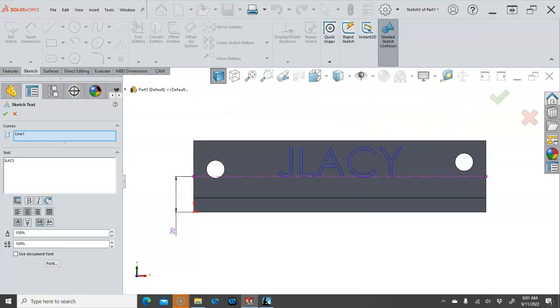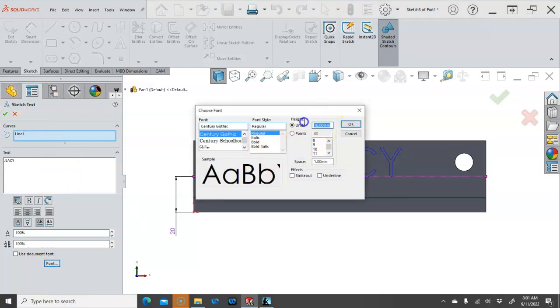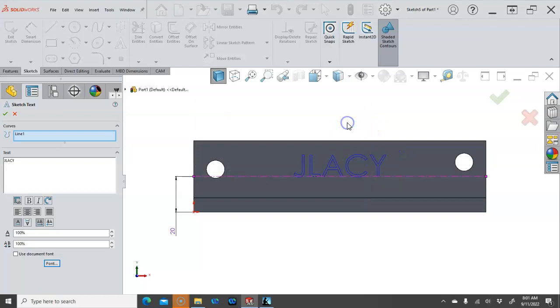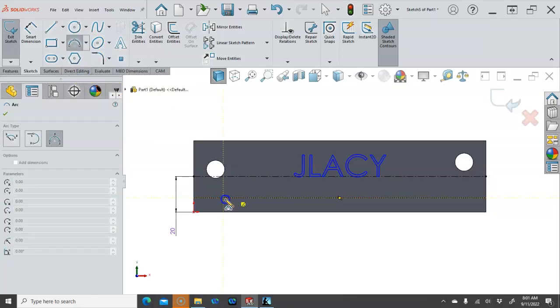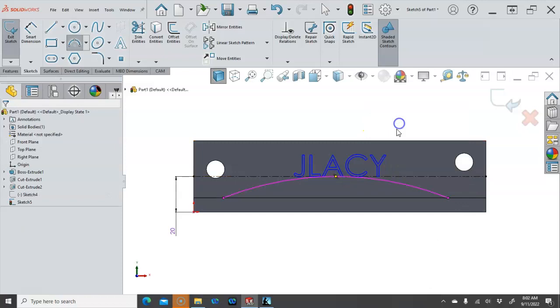And then we go back and, well, actually I should make it smaller so we can do the arc example. Okay, then that gives me something that I can extrude. If we go into, let's do a 3-point arc because I think I'll have probably the best control over it. So kind of, well, we'll make it tangent.